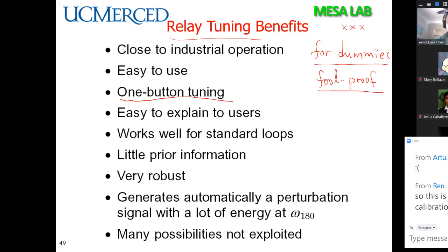You have that button that says, I want to retune. Just press it, and it will do it automatically for you. That's called auto tuning. There are some dedicated books on this topic, even 300 pages long, though here it is just 3-4 slides. It's also easy to explain to users, and works well for all the standard loops with little prior information, okay? Just to make the system have a sustaining oscillation. And it's usually very robust.